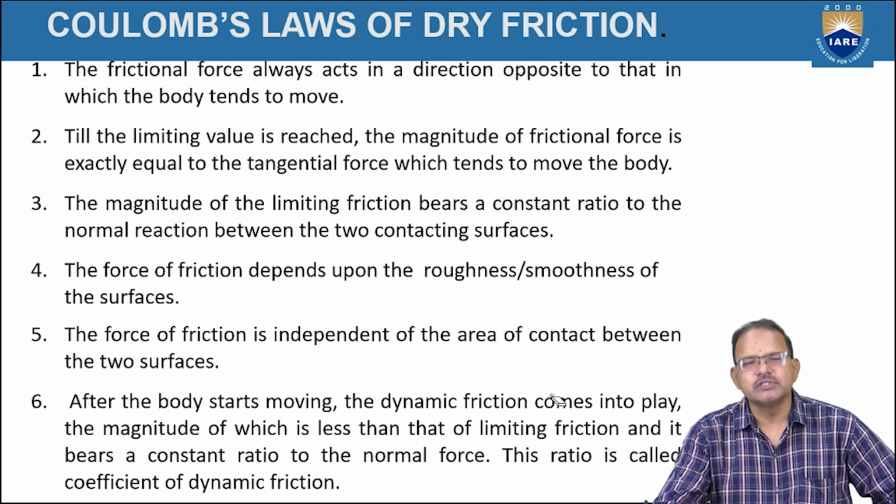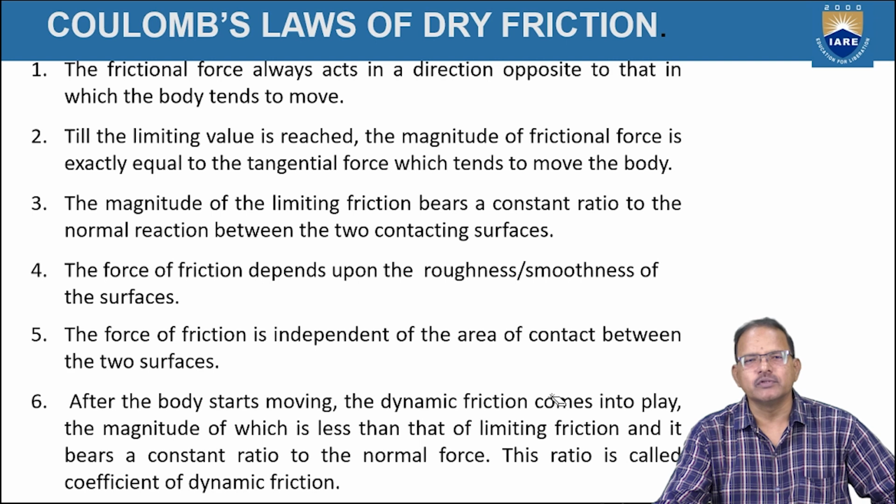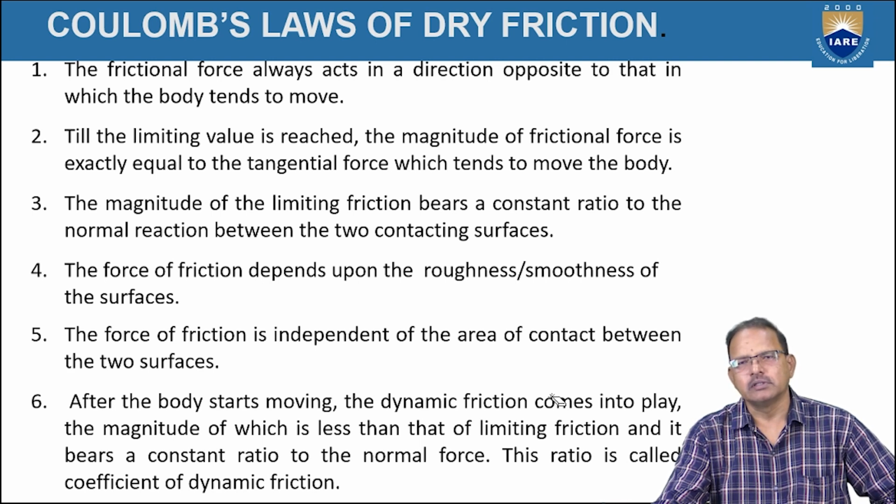And when the applied force is 0, the friction force is also equal to 0. And when the applied force is increased gradually, the friction force experienced between the body and the contact surface also increases. When the body is about to move, it has maximum frictional force, which is called limiting friction.